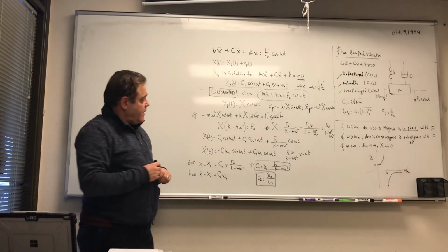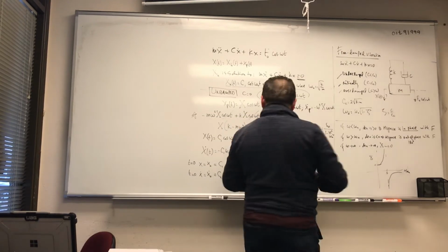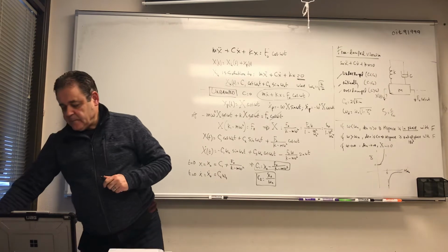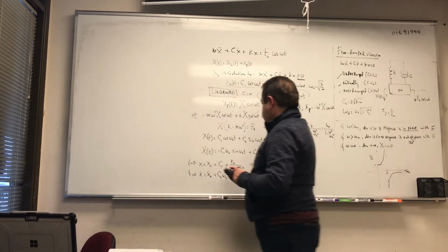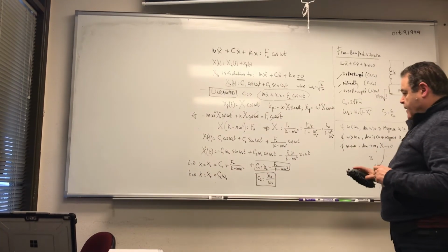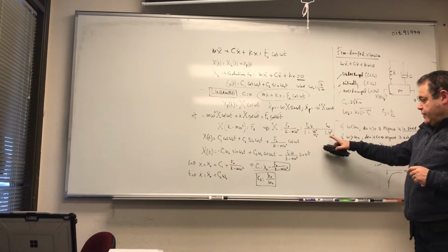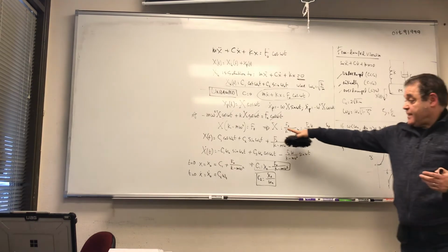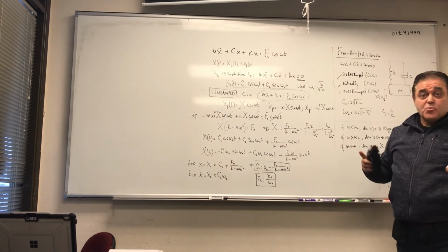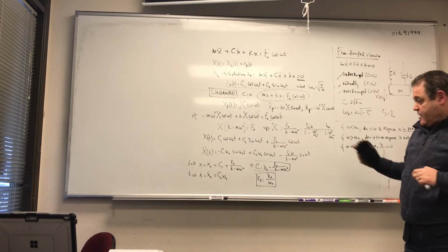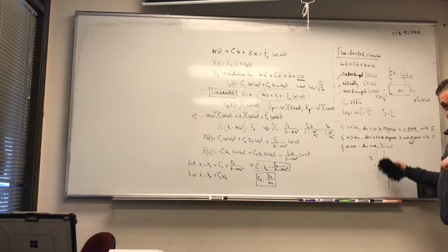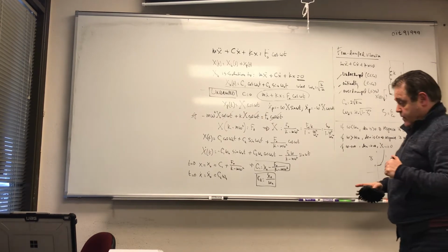The only thing that's going to come into play when you have damped vibration is... And again, just before I go any further, remember as omega approaches omega n, you see that the amplitude just goes crazy. That's what resonance is all about. That's why we try to avoid this frequency here as the forcing function. As far as possible from it would be great.